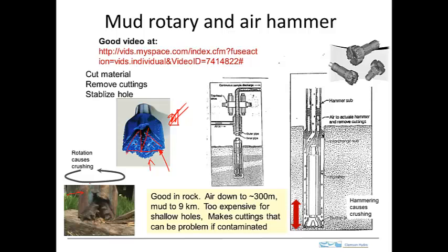As this bit rotates, these cones are rotating, and this little piece of carbide is moving around and going to push down onto this bottom surface, just with a small degree of additional rotation.